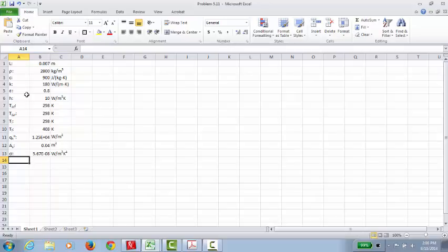Notice also that all the temperatures are written out in terms of Kelvin because you need to have everything expressed in terms of Kelvin because of the radiation term. So in order to calculate the effective radiated heat transfer coefficient, you need to have everything in terms of Kelvin. We have some other parameters we have to define here. We need to come up with a time step value. We can start with 5 seconds, and we'll see how well that works.